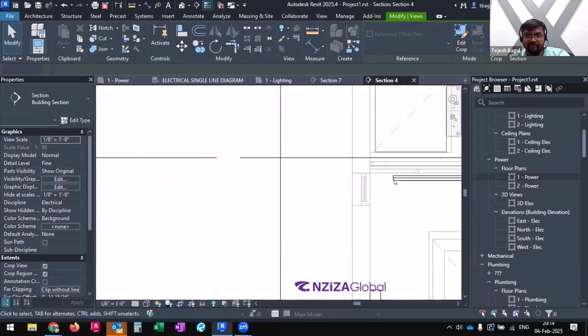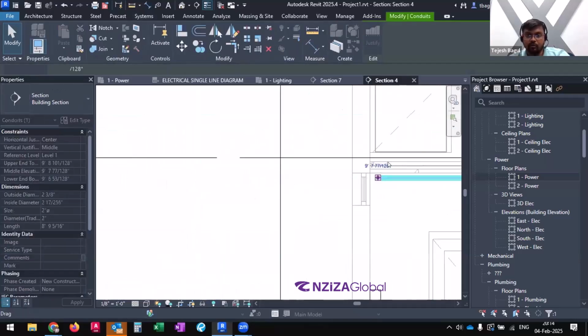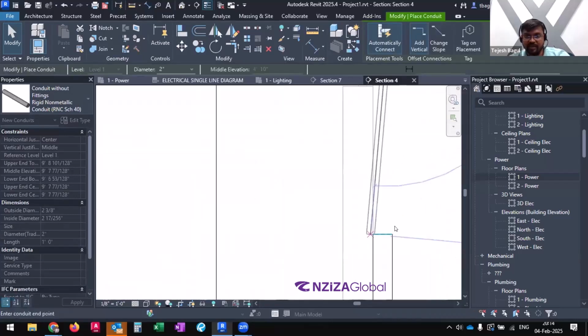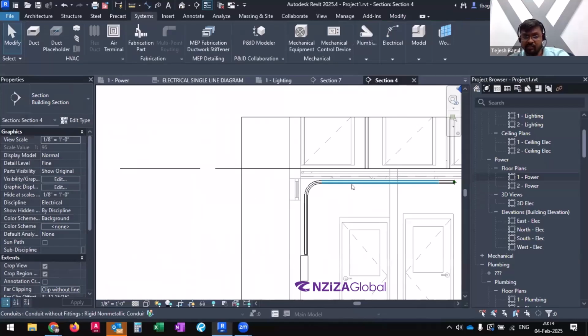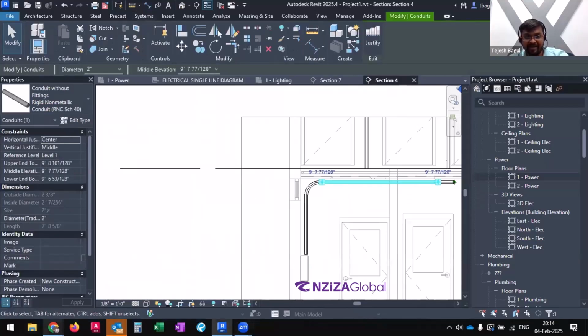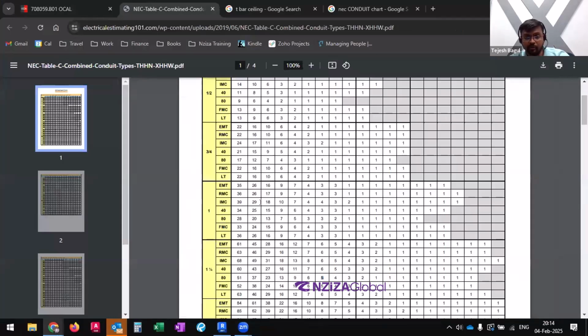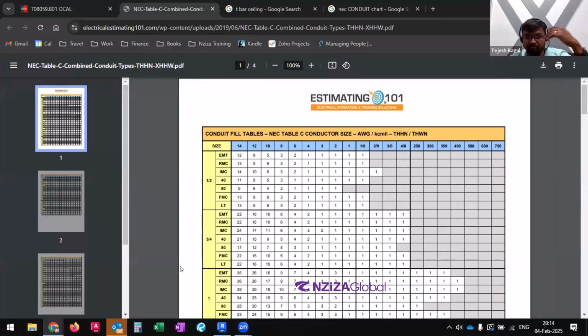And this is the conduit that we are drawing over here. But again, talking about coordination, this is something that the electrical contractor will be taking care of. So this conduit size will also go back to our given conduit size over here. If you are using a 12 American wire gauge, because we are not going to go to each and every receptacle to be of a different kind of size, right? We need a standardized size of 12 American wire gauge if you decide that is your given size.